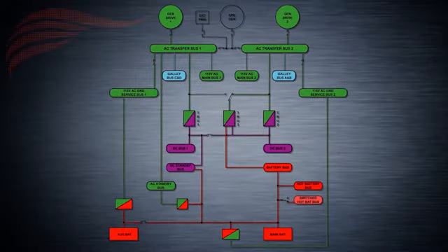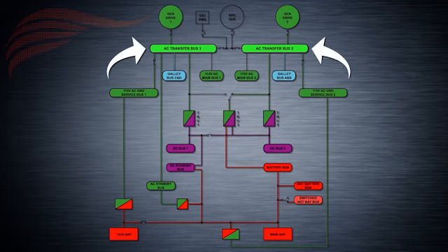The AC electric system has two primary buses that take all the generated AC power and divide it amongst smaller AC buses. AC current is supplied as 115-200 volt 400 Hz power. The two primary AC buses are known as AC transfer buses 1 and 2.